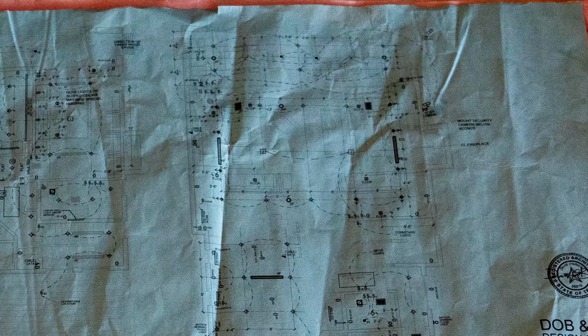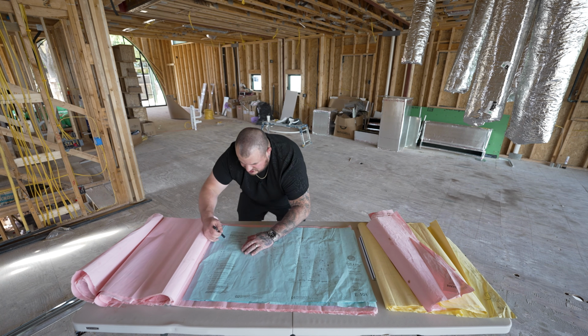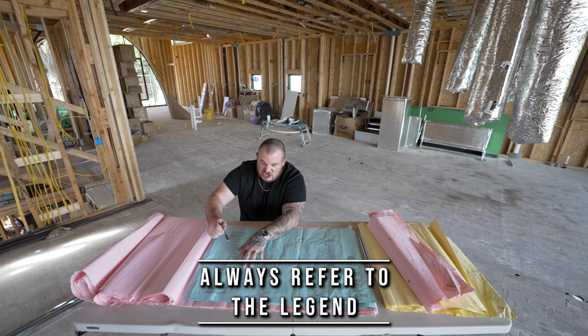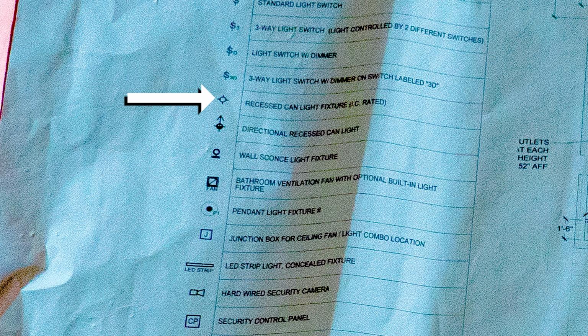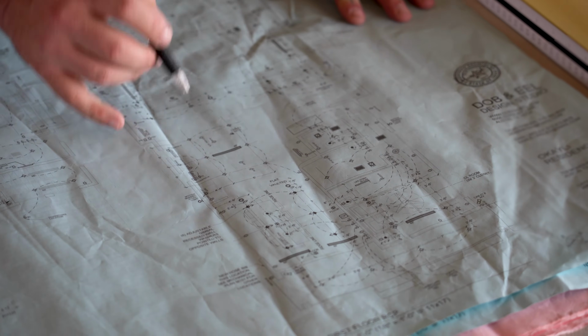The first thing you need to do is look at the lighting legend. So this legend, it's gonna show you what the symbol is and what it means. This dollar sign is a standard switch. The dollar sign with a 3 is a 3-way switch. Everything that you need to know is right here. So now when you go back on this plan, you see that this little circle with a hash mark is a can light. And you see those littered throughout the whole electric plan. You know that those are your locations.